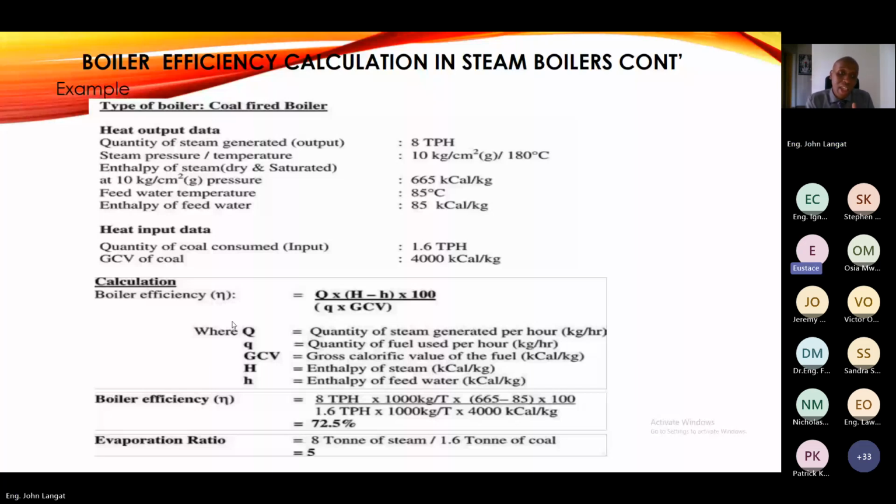But this is on the premise that you are going to do steam management. So maybe consider the initial capital cost and recouping that amount, because it's not something that will save energy itself, but it will give you information to make decisions on how to save energy. The cost-benefit will not be a return on investment as such, but you'll use it to do a proper energy audit and take measures. It's more of a necessity than just an additional thing to the steam system. I guess those costs for purchasing meters fall under sunk costs, which you just have to incur.